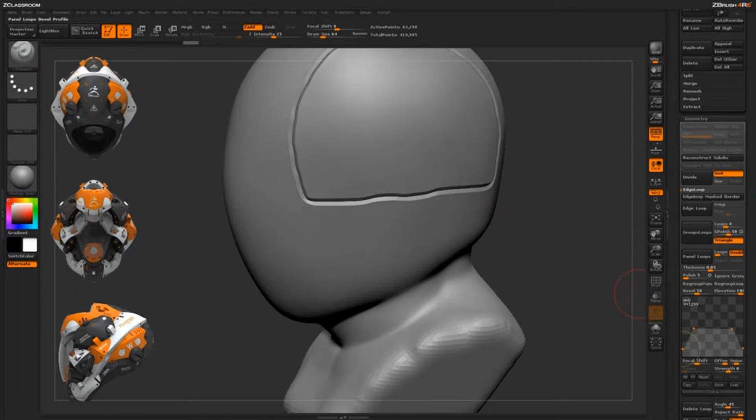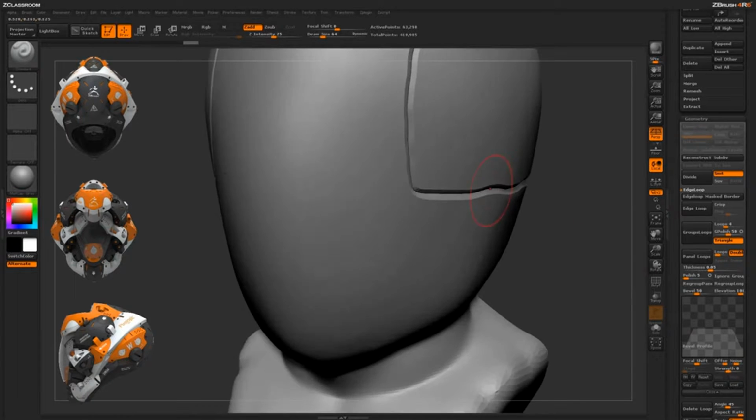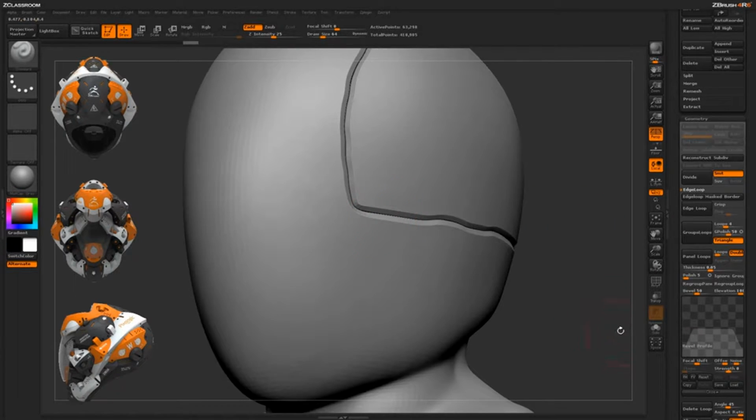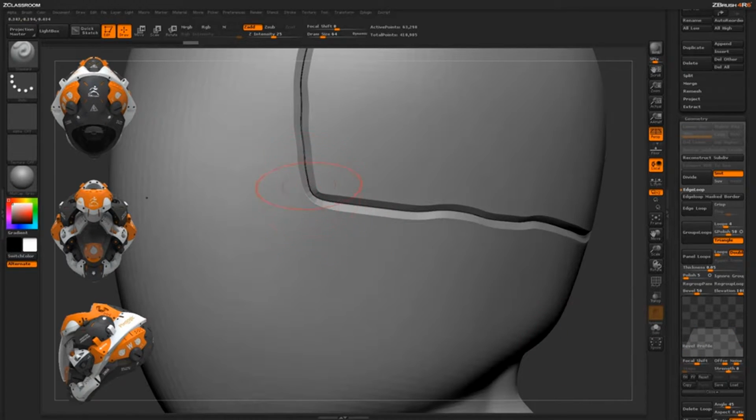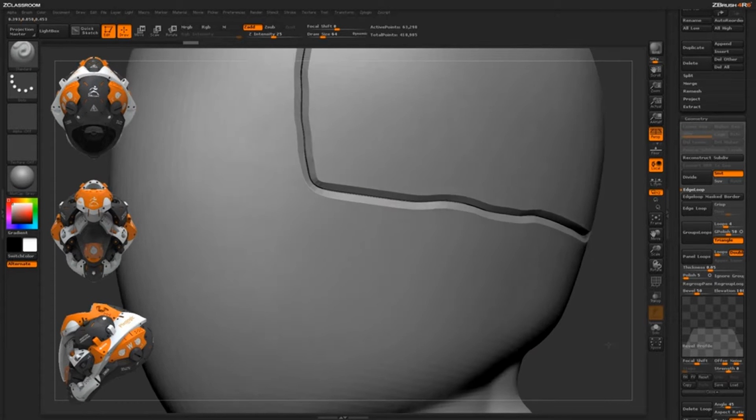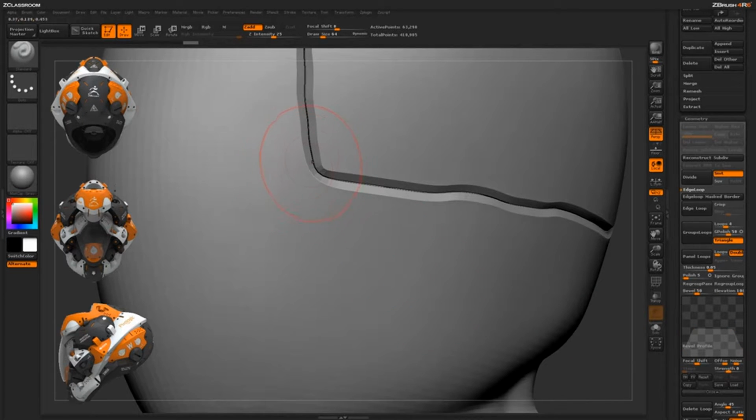So you can see, just think of the tapering along the side, and that's going to determine the actual angles that are going to appear on those panel loops as they're created. Another thing with this is that the graph is actually, if you think of it as a value of 0 to 100, the 50% line is going to determine how much each panel embeds into the next panel beside it. So right now I'm a little bit below that 50% line.